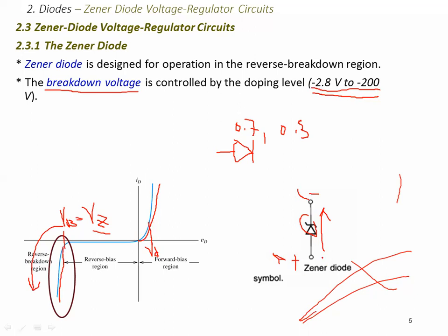So I'm saying if you connect it in this forward bias, it will just reach any one of them depending on the semiconductor that has been used, and then it maintains that voltage. But then we're also saying if you put a positive on the cathode and a negative on the anode, we are reverse biasing this Zener diode. All you need to do is to reach its breakdown voltage. Once you reach its breakdown voltage, it maintains a voltage equal to Vz across it while the current will be